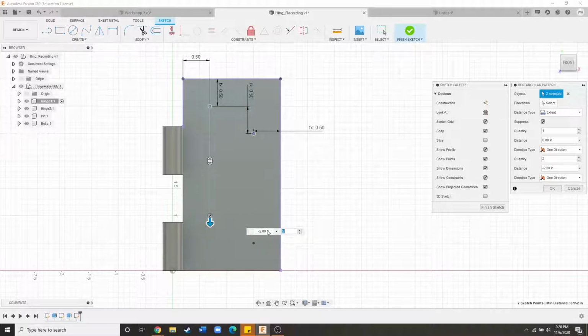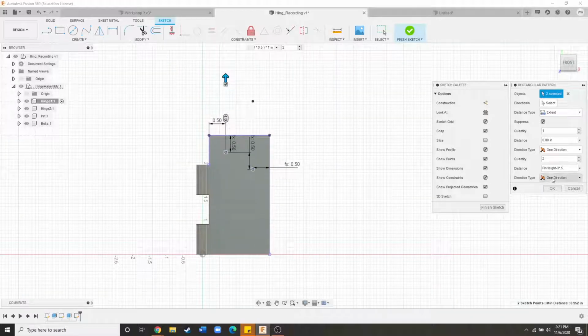So it works out to be -2 inches just because our pin height here is 3.5 total inches. Then you have 3.5 minus 0.5 for this, minus 0.5 on this lower portion, and then minus another 0.5 in between these 2 points. So maybe that's a little bit confusing, but I'll write it out here. So we've got pin height minus 3 times 0.5. So you can see it's going the opposite direction that we want it to.